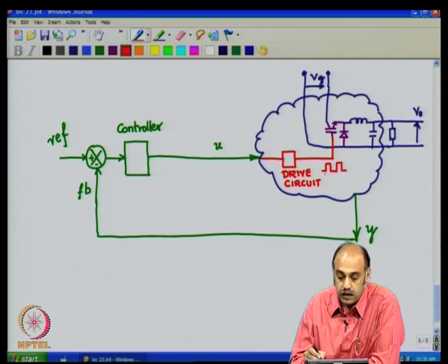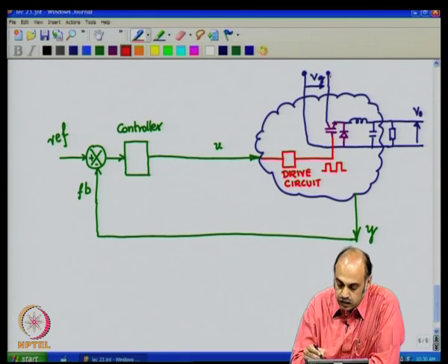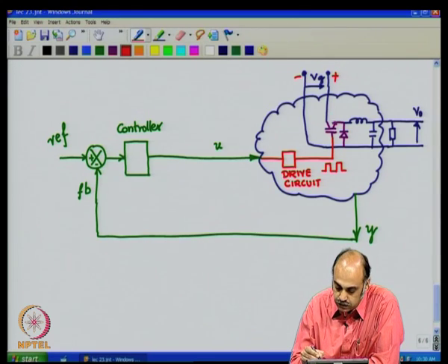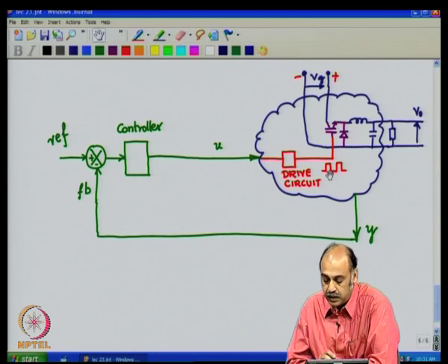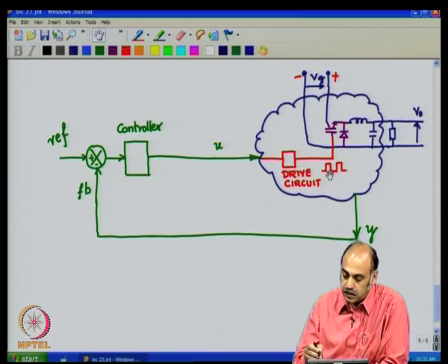So, whenever the pulse is high, this switch is on. The moment this switch is on, this is positive, this is negative. This positive is going to come to this point, the diode point, and the diode gets reverse biased off. So, therefore, it is off. So, this would be like your first mode of operation, where the supply is directly going to the LC. And in the second mode, the moment this is switched off, there is a polarity reversal of the inductor voltage, due to the energy storage within it, it will freewheel through this diode. Diode is automatically back into action, it is conducting, and also the switch being intentionally turned off during the 1 minus D period. So, this is the kind of practical situation you have.